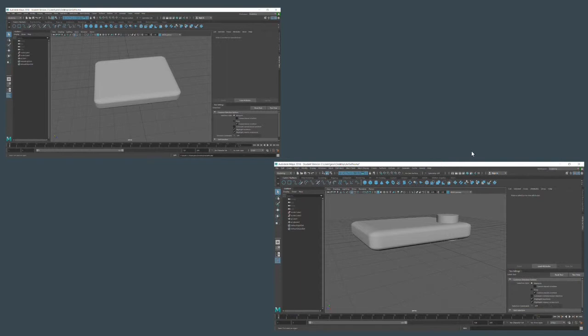When it does the difference, it basically extracts out of the first shape whatever the second shape is. Since they are cylinders, it extracts out a big hole or circle in the rectangular prism body, which ends up creating the holes for our propeller.